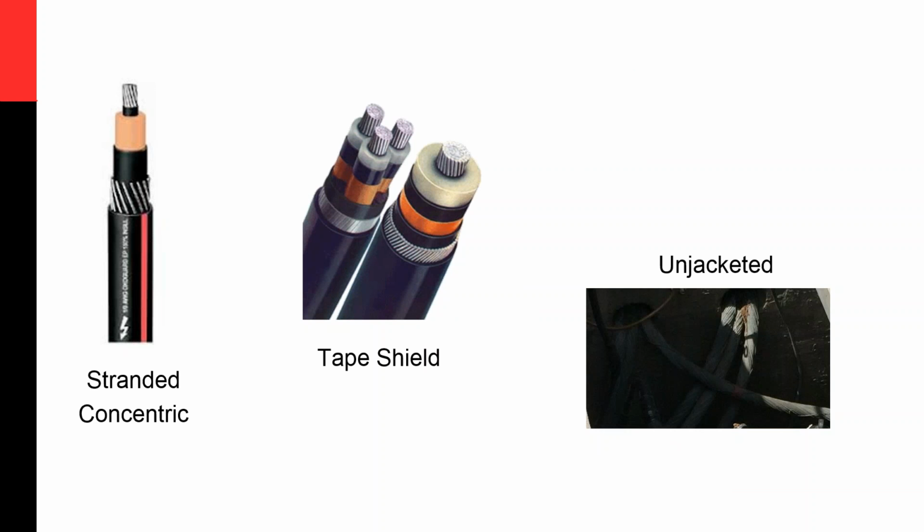As I said, on the left you can see the wires, actual wires. Then you have the tape in the middle, and the unjacketed cable. I only found a picture, not so much an illustration. And what you see there, this gray, this is the corrosion of the actual neutral. This stuff can actually corrode away. It can be literally eaten away by the elements, by chemical reactions in the soil, and that can cause problems.